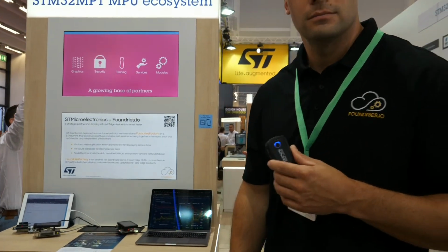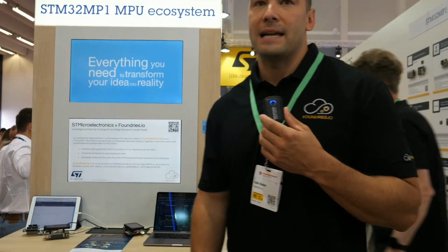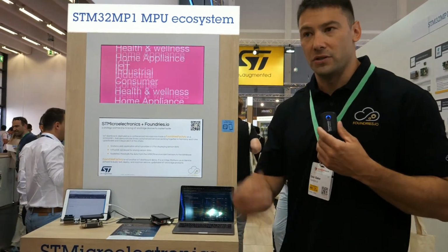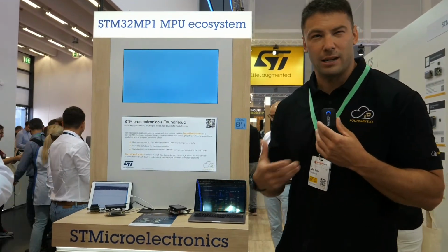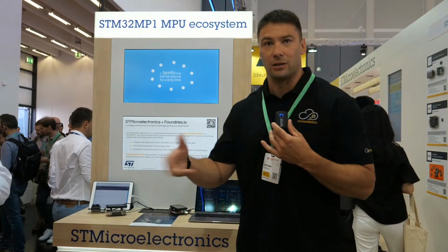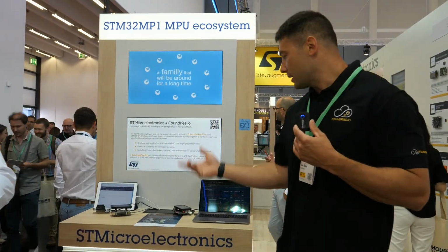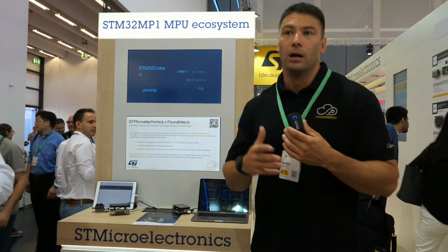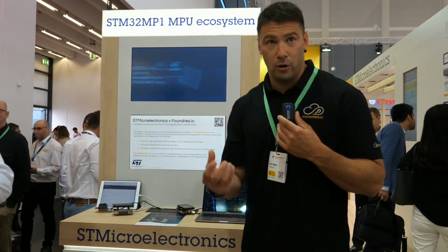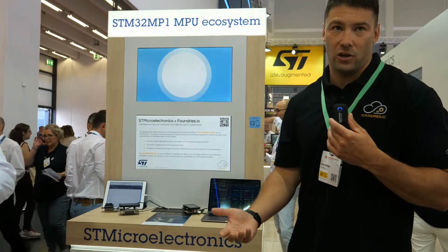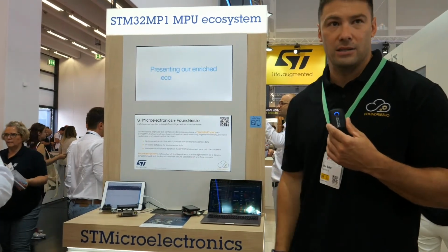But it has to do around the Linux. Yeah, I mean, so that's how Linux facilitates the firmware down to the system, and then once it's to the system, we have a really generic way to allow our customers to integrate it, because a lot of our customers may use CAN bus to signal an update, right? Or they may have a direct connection over like I2C, and so there's no generic solution for that, but what we can guarantee is that we'll get the payload, their M4 firmware that's signed, to the device securely, and then from there they take it, and it's their own business logic.